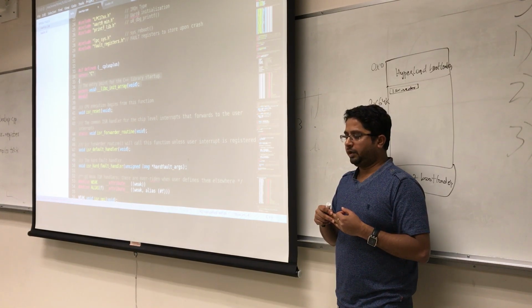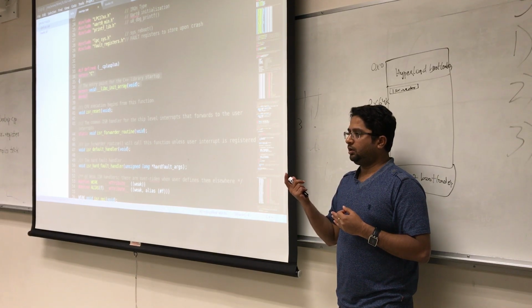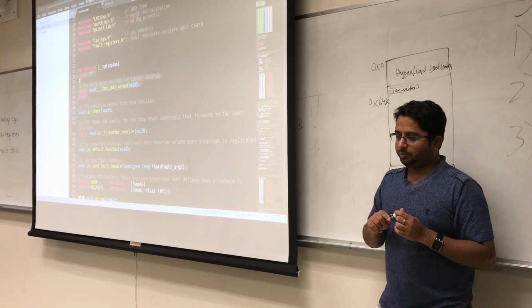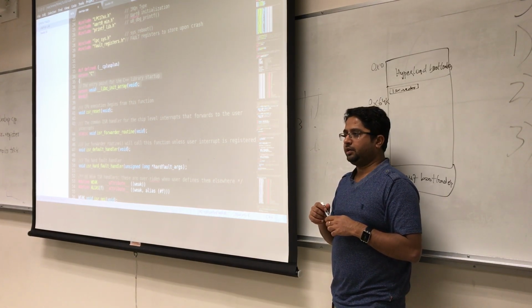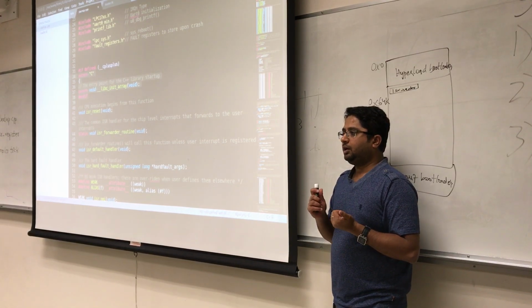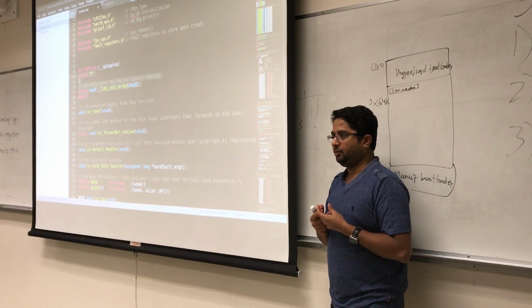So for example, say you have port 0.1, which is a GPIO, or P2.0. If the GPIO pin needs to do something when it senses a rising edge or a falling edge, then you will say, this is the pin number, this is the edge that it needs to detect, and this is the function, the ISR routine that it needs to perform.